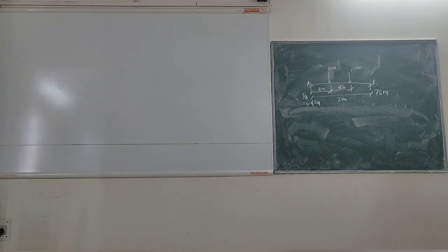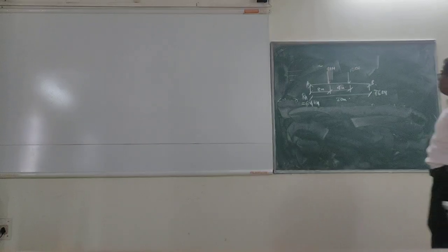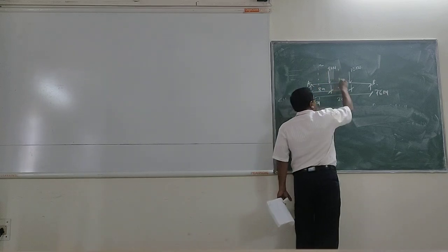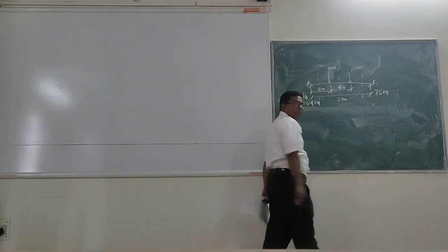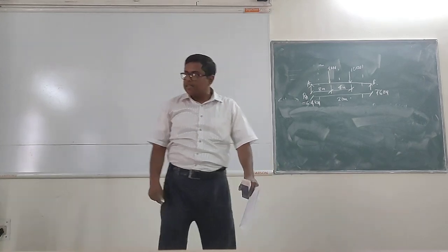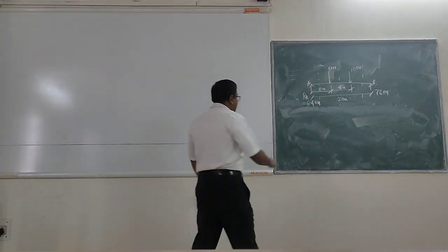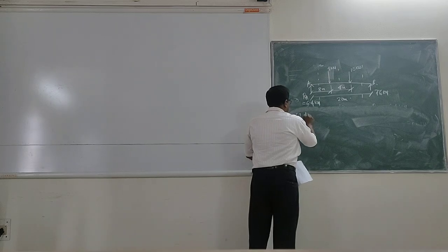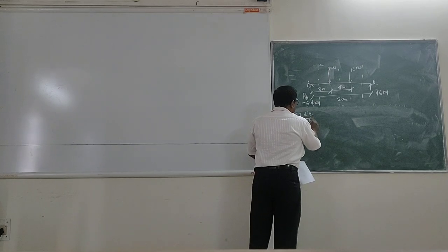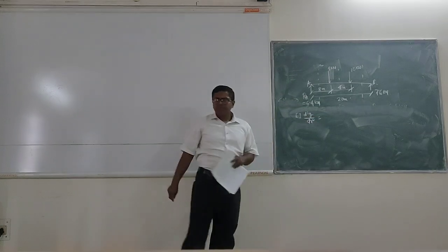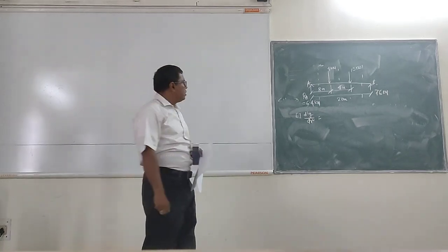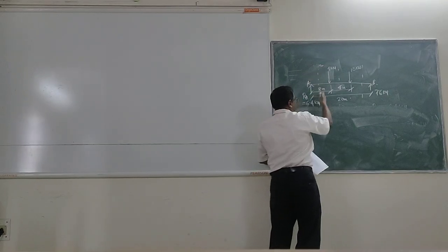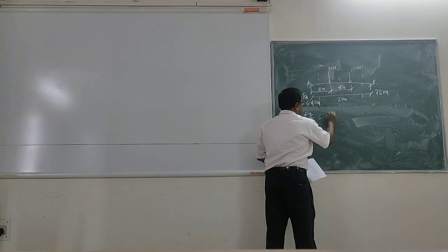So the general equation you have to write, right? General equation means my section X can be here, here, or here. So at any point the section X can be there. So what will be my generic equation? The generic equation will be EI d2y/dx2 equal to how much? RA into X first. If I take X over here, RA into X, how much is this?